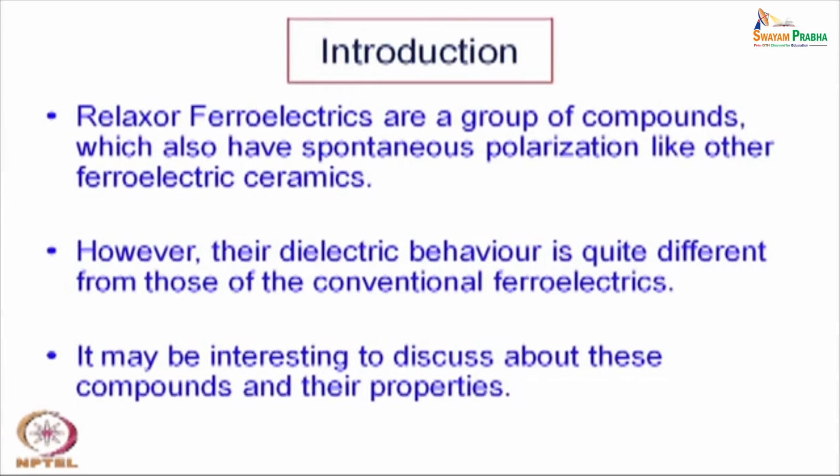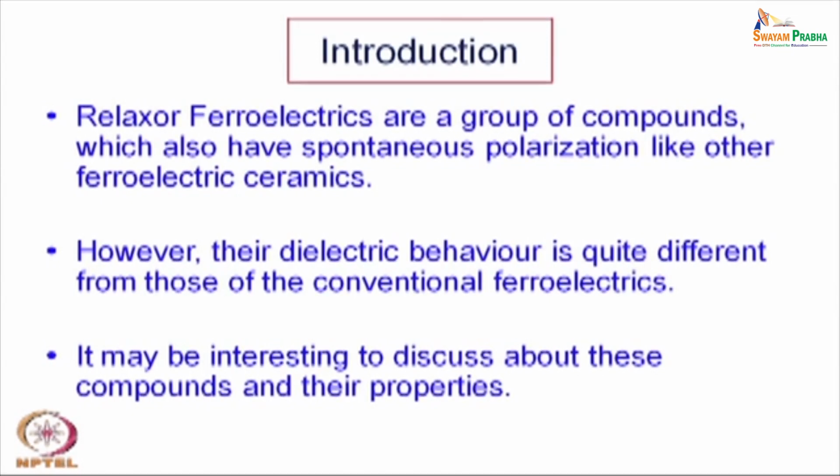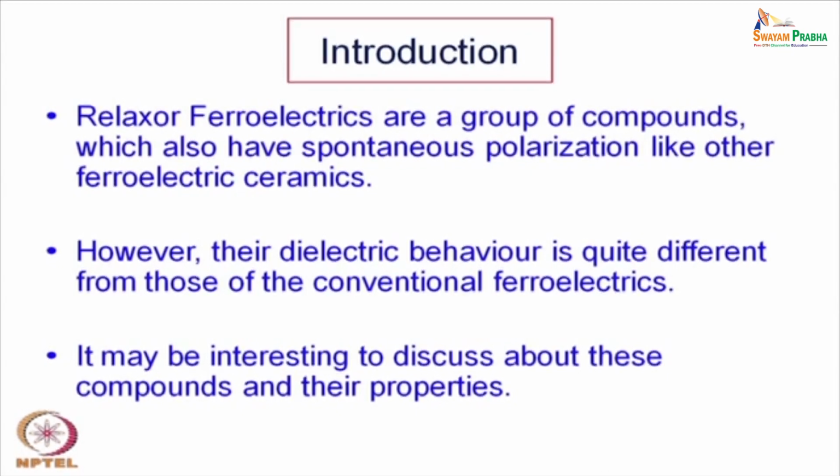To introduce this group of materials, Relaxor ferroelectrics are a group of compounds which also have spontaneous polarization like other ferroelectric ceramics. One of the basic characteristics of ferroelectric material is spontaneous polarization even in the absence of an electric field. So, these ferroelectrics called Relaxor ferroelectrics also have the same property. However, their dielectric behavior is quite different from that of the conventional ferroelectrics.